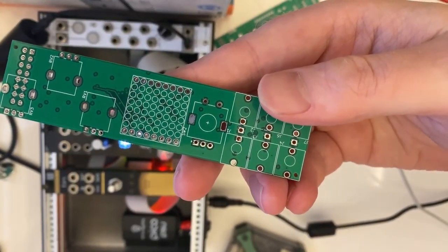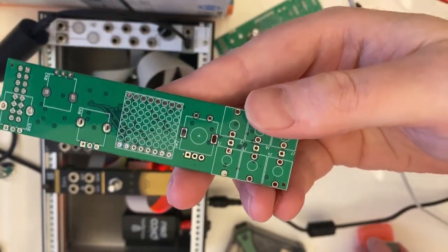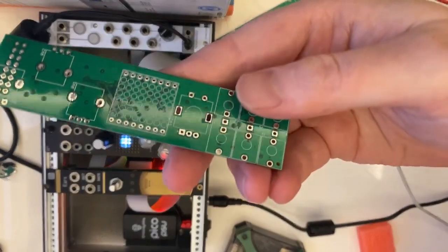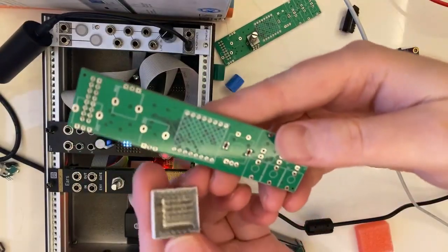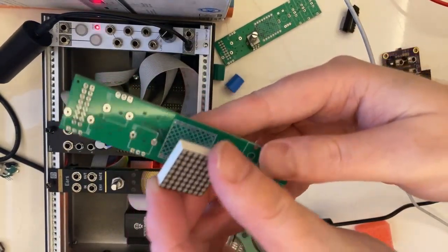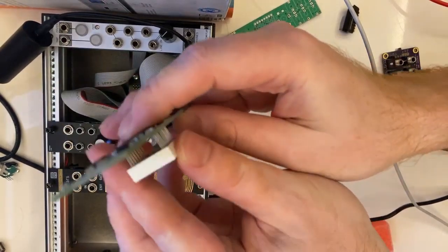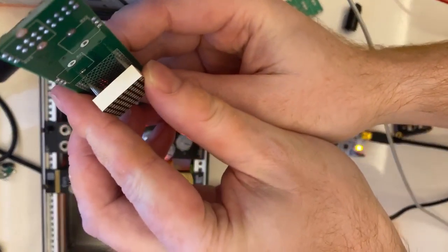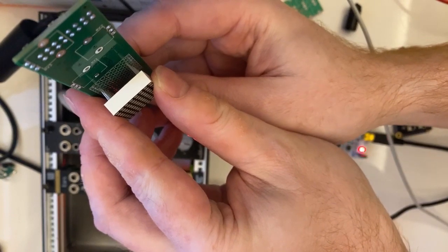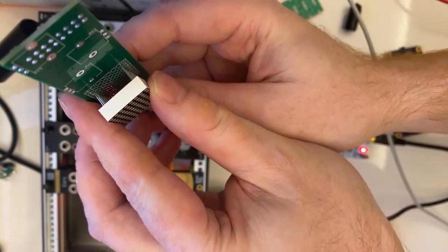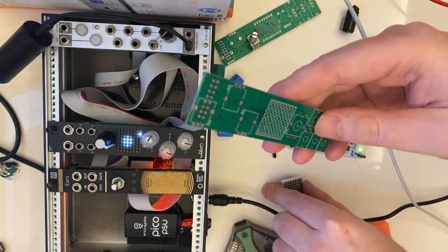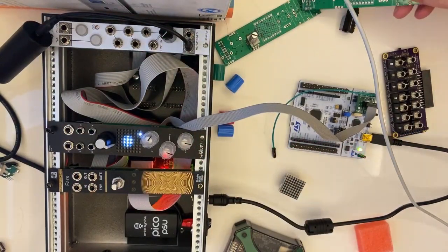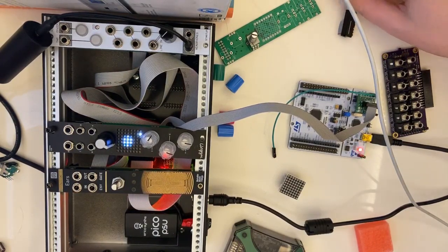So you can see I made a footprint of 8x8 LEDs, and those LEDs are actually in the right places, but I assumed that the pins go all the way sort of symmetrically 8x8. Turns out, no, they don't. The pins are actually narrower. I don't know if you can see this if I put it that way. The pins are actually narrower, they're not square, basically. But luckily, you can just bend them. And so on the actual piece, because it stands off the PCB sufficiently, I got away with it. So that was mistake number 2.